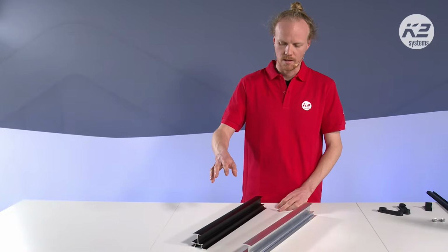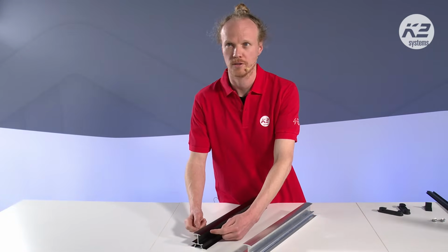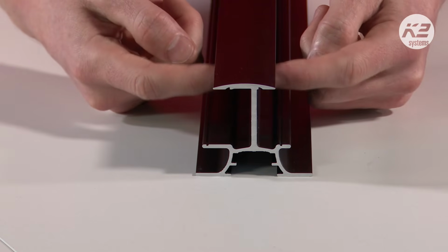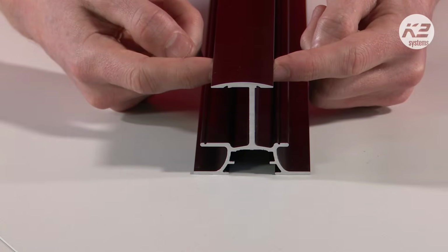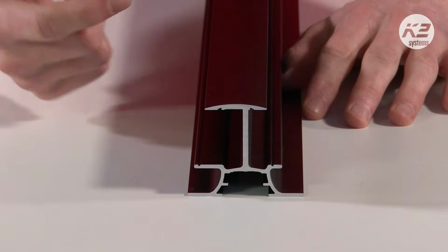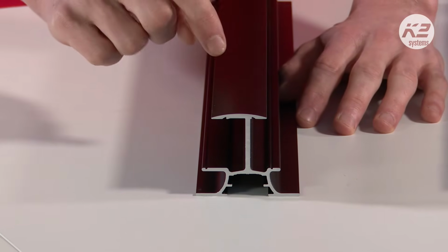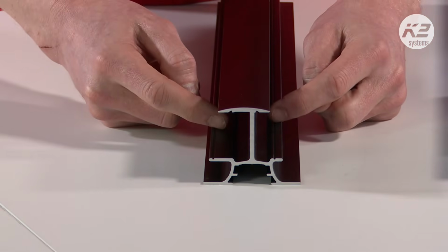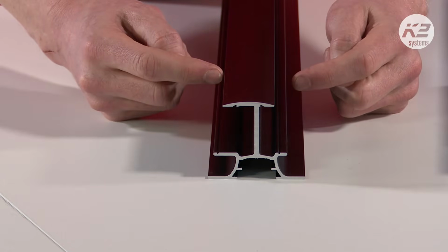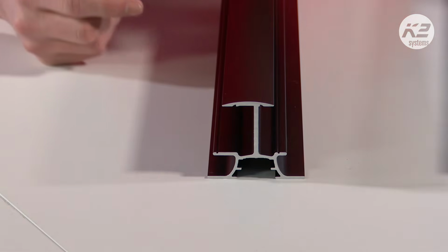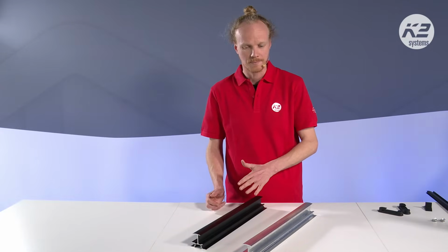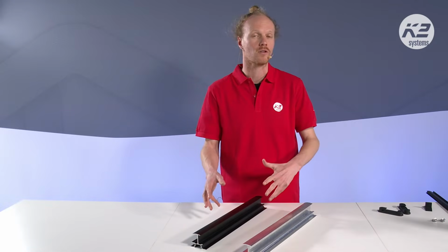And what you'll notice, if we can just zoom back in here, is that this distance here is going to be determined by the panels we use. When you have a clamp, you can usually just tighten the clamps higher or lower depending on the module frame. But this specific rail is only suitable for one module width, because this height here must be equal to the module height. So we have three options, the 30, 35, and 40, and they come in different lengths, and we have the silver and the black.